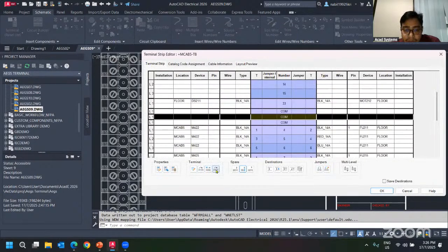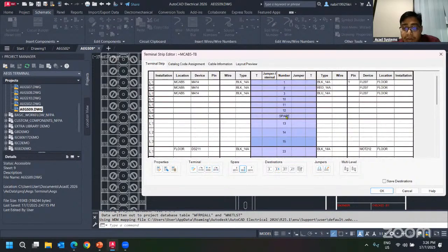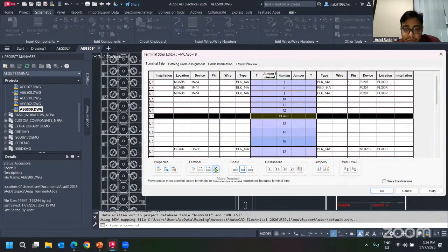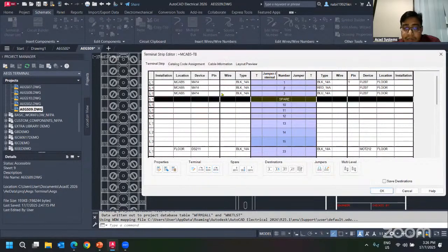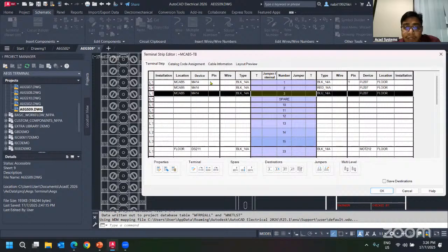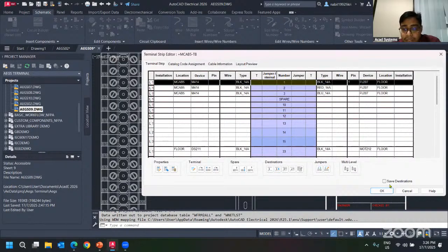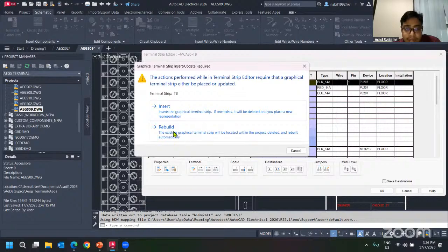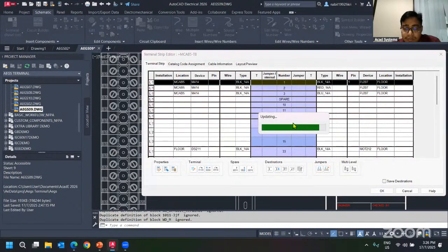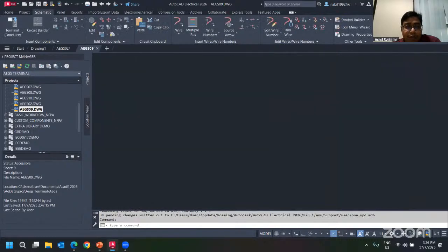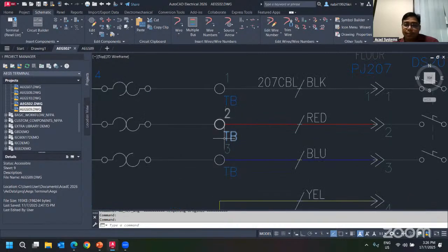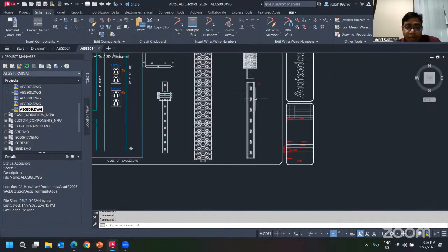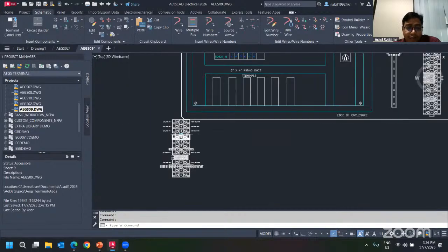Okay, so over here, terminal, if you want to move it around, so maybe spare here, I want to put it below this tree here, I can just use move terminals. I can pick, say, below this part and it moves. If I have this tree here, this one should be, let me just rebuild. Okay, so the tree one that I saw before should be these 3 terminals over here. So if I go back here, you see that it's actually not yet associative.